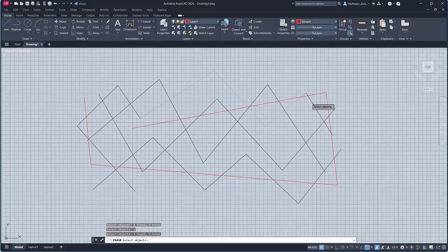If I keep going and I don't want all those lines that I picked, this time, notice it says it's found 5. I'm going to select the undo command, and you'll notice the command prompt completely changes because what's happened is it's undone the entire command sequence and got you back to the command prompt.